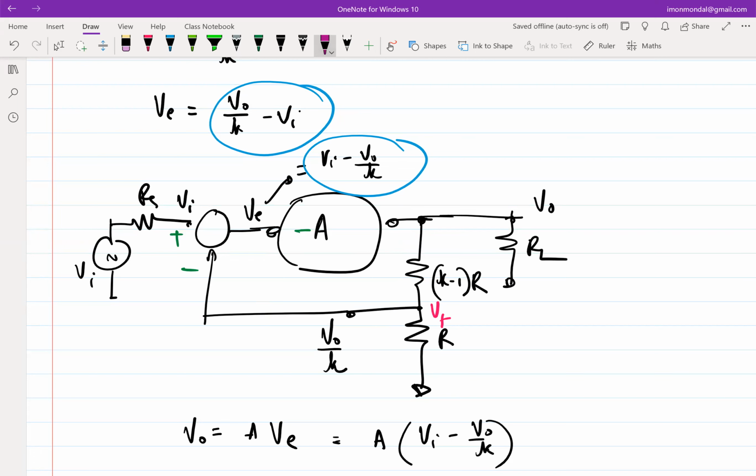Let's say we give excitation here, and the disturbance is going up. So the output V0 will go down, Vf will go down. And when it goes through that difference block, it's going to the negative terminal, so it's going to go up. Correct? Which essentially means that we'll have to change the signs of the difference taking block. Okay.